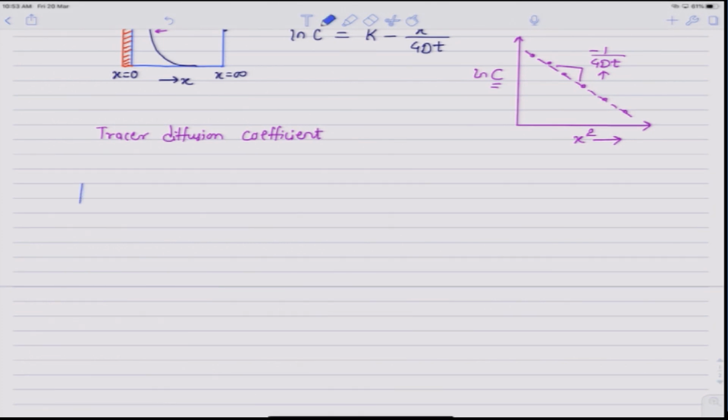So, if we want to describe a typical experiment, say we want to determine the impurity diffusion of A in B, this may be pure B or it can be a homogeneous alloy in which A is an impurity. It can be, for example, diffusion of copper in pure nickel, or diffusion of copper in a nickel zinc alloy. Of course, the impurity diffusivity will be different in both cases, but both are characterized as the impurity diffusion coefficient of copper in that particular lattice or alloy.